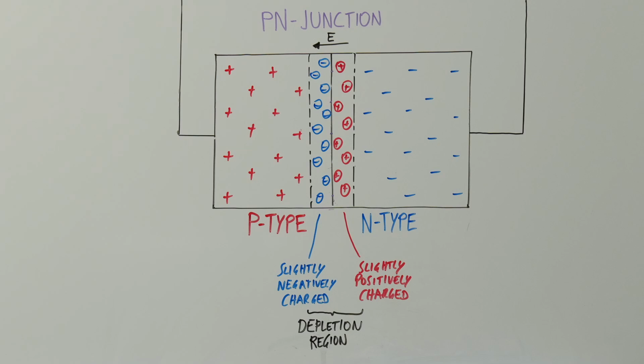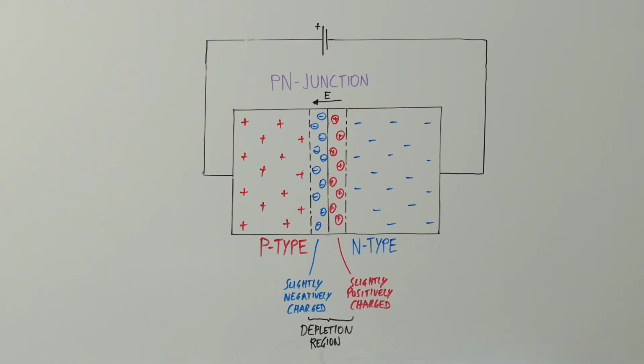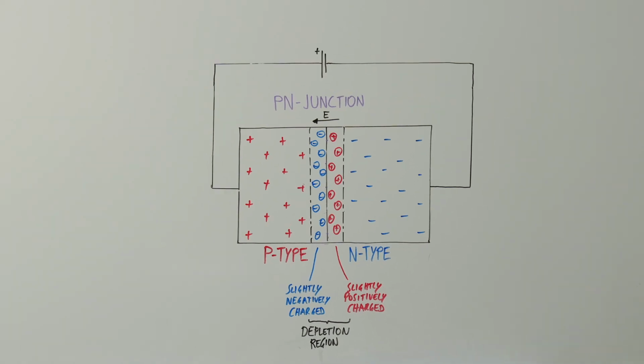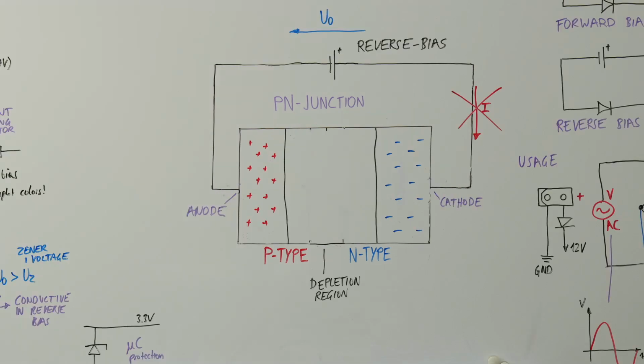When placing an N-type semiconductor next to a P-type semiconductor, we get something that is called a PN junction. Some of the electrons move to the P side to fill up the holes, which creates an electric field that prevents further movement. If we apply voltage in forward bias, this barrier can be overcome and the material becomes conductive. If we apply voltage in reverse bias, the holes move to the negative side while the electrons move to the plus pole of the battery, which makes the barrier even bigger and allows no current to flow.